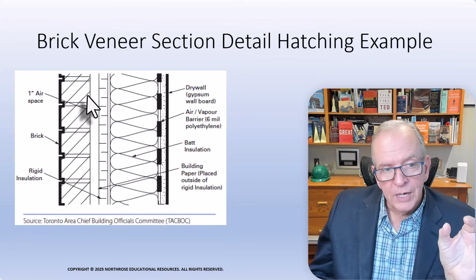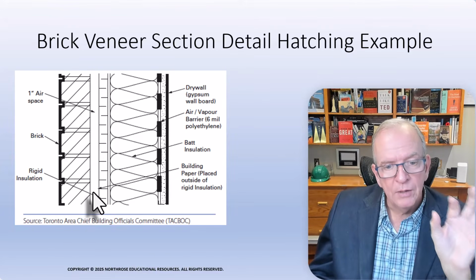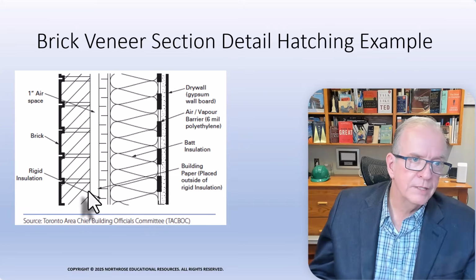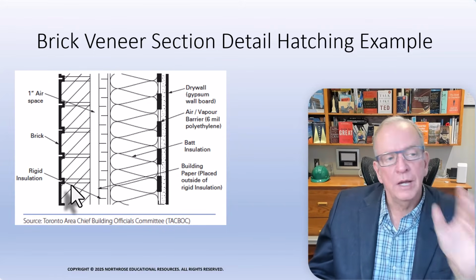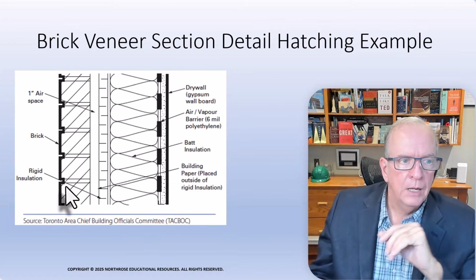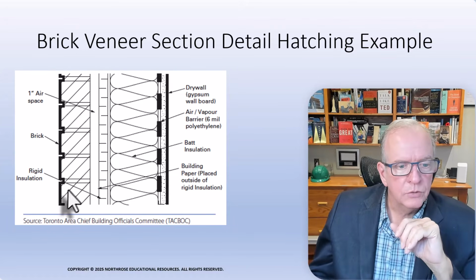So if any moisture gets down, it can travel down, and then there are weep holes where it vents out. We'll look at that in further videos in this series because I have whole chapters on framing in the book. We're just looking at details right now.